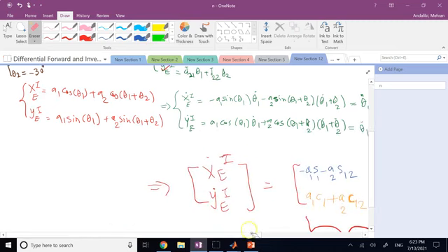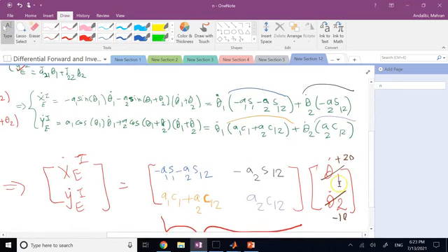What you really need are those Q dot values, how fast to turn each joint in the robot. And you can find that, again, we call it inverse velocity, and for that you need the inverse of this Jacobian matrix. Okay, so we'll talk about that and about singularities and stuff, but I just want you to see the importance of this guy to take your space from joint space to the workspace.